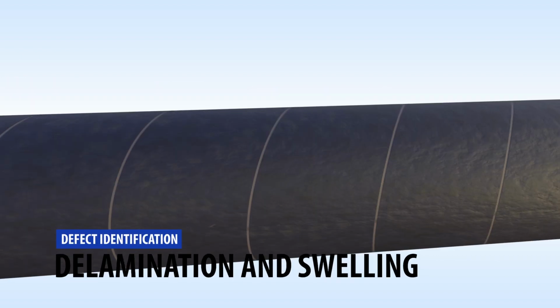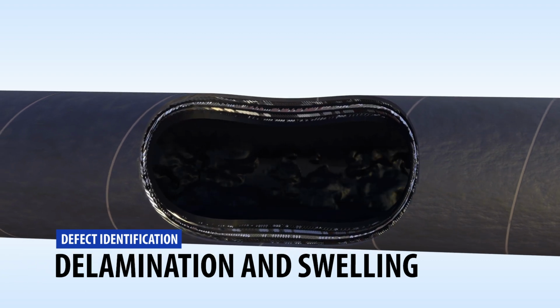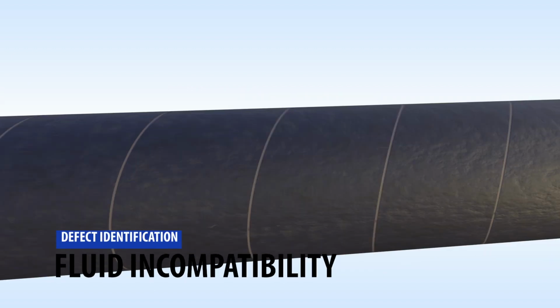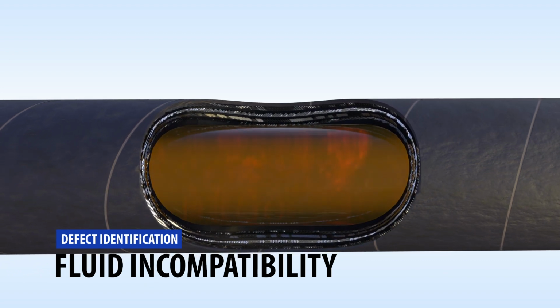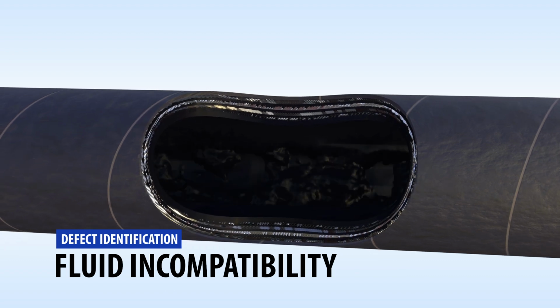Delamination and swelling is caused when the fluid is incompatible with the inner tube material and the inner tube may partially wash out. Fluid incompatibility occurs when the incorrect hose is installed for the application. Refer to the Pertec catalogues to find the correct hose for the application.